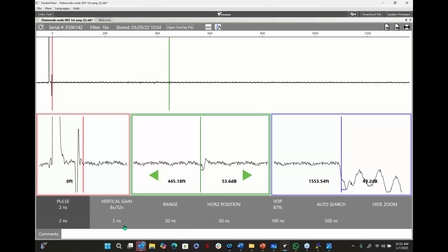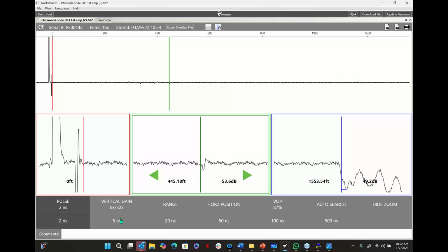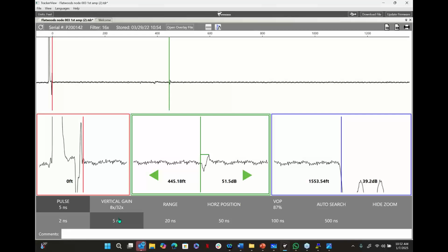It never occurred to me, look what happens when I change this from a 2 to a 5 nanosecond pulse width. Because on the Springbok, I can. I don't got to be out there live. Because of the frequencies, this stands out cleaner with a 5 than a 2. Did you see that? Let me do it again. That's a 2. That's a 5. A little bit cleaner, right?